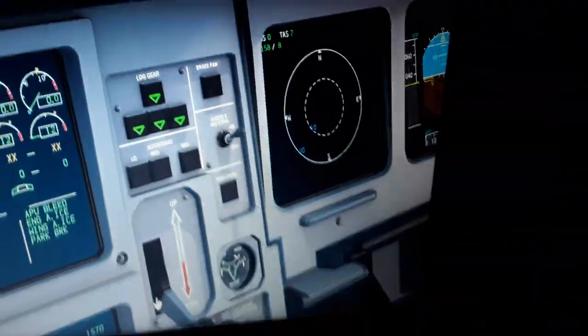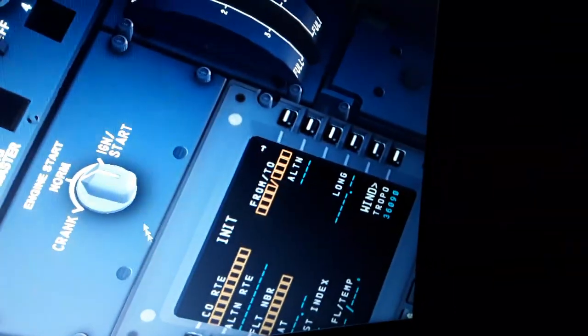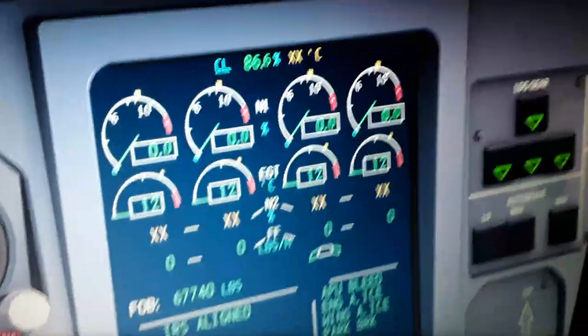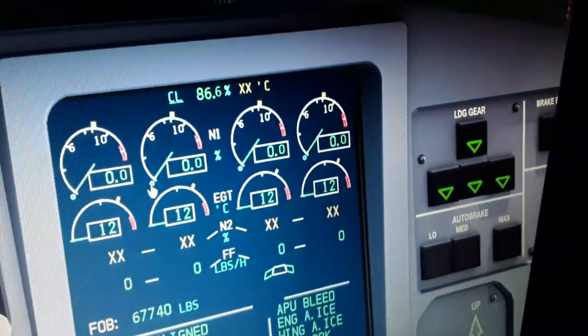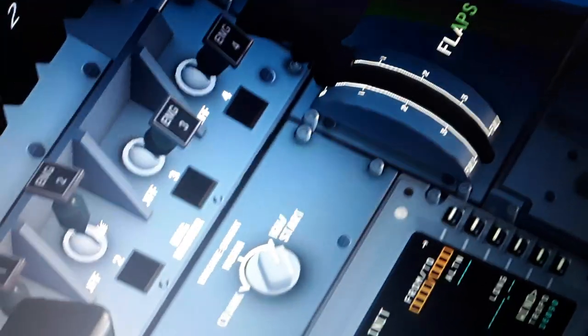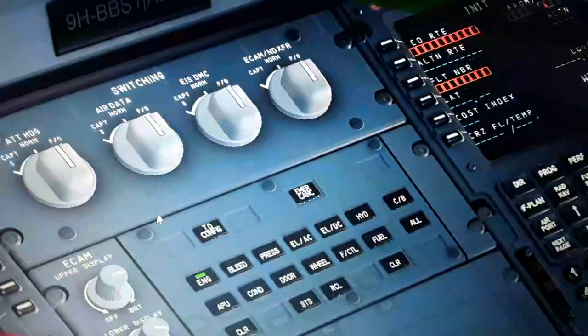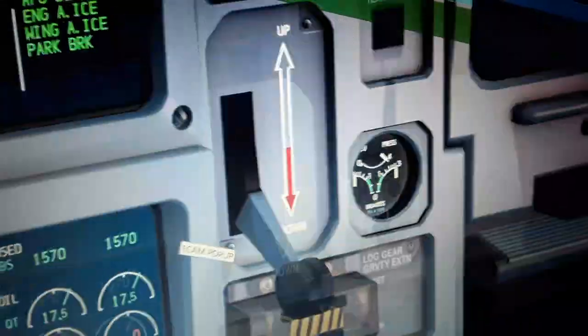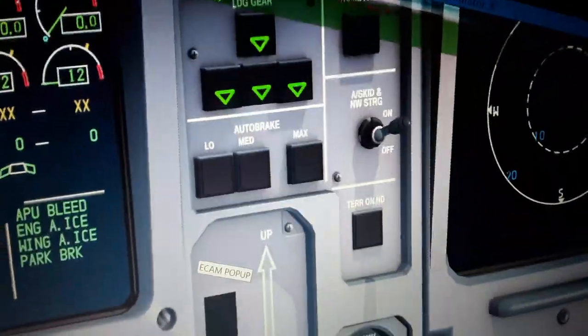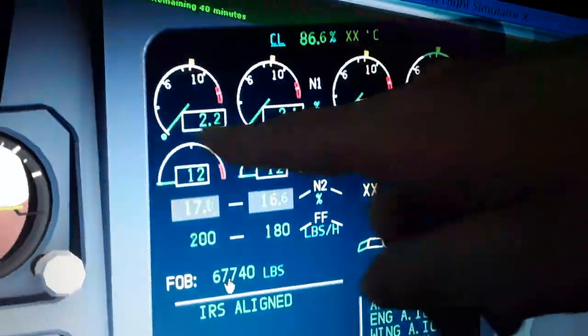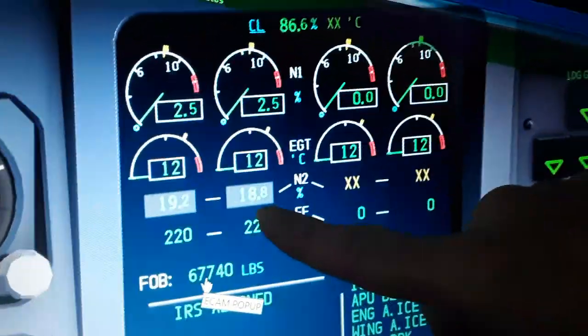So we can use this master switch into the ignition start, starting the left engine first. The left wing engine 1 and 2, excuse me. So this is armed now to the start mode. If we start the engine master switches 1 and 2, we're going to see here we have a reconfiguration and we have the initiation of the admission of the compressed air. We have the FADEC controlling this automatically.